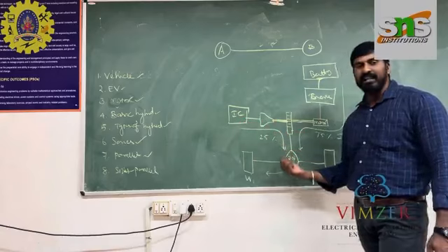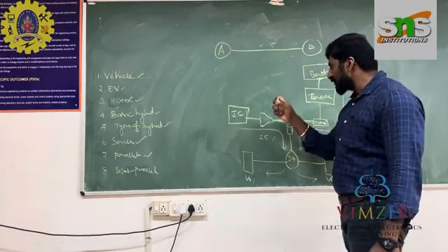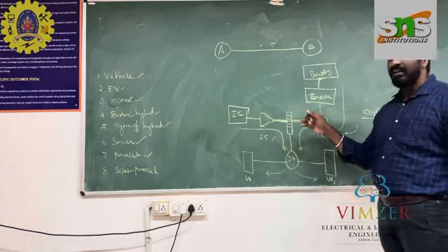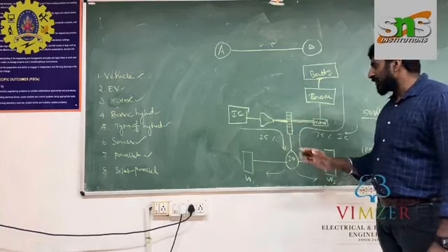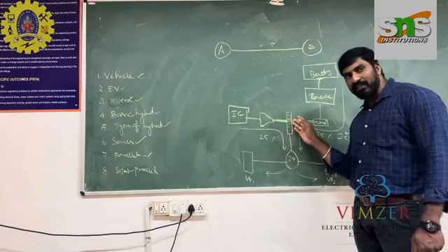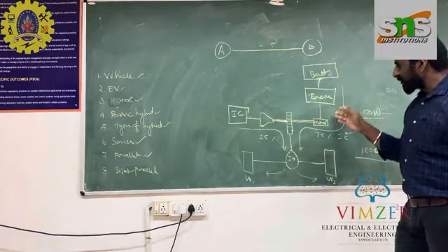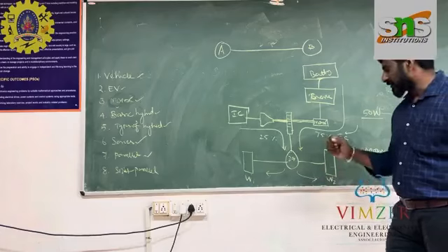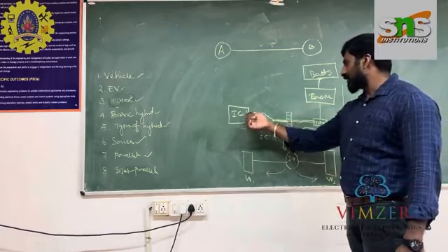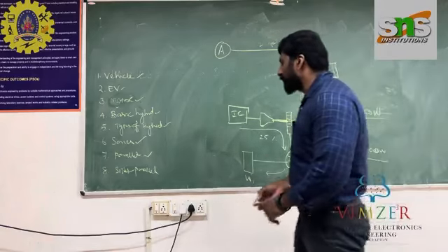The internal combustion engine delivers 25% of the power. This power is taken from the internal combustion engine through the gearing arrangements and gearing mechanism. Here the gearing mechanism has two different kinds of sources. For example, if we do not need the internal combustion engine, the gearing mechanism can easily cut off the engine input, and the vehicle is driven only by the battery, inverter, and motor. And if the battery power is going to be 0, at that time we can run on the internal combustion engine and gearing to the wheels. So this is called a parallel hybrid system.